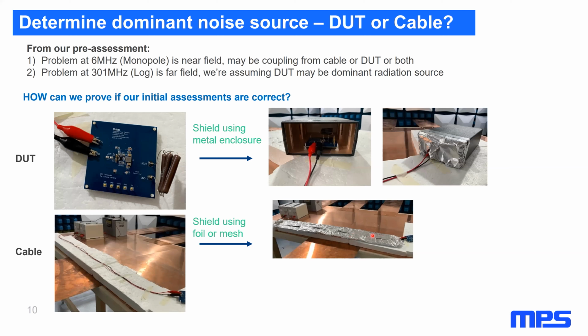I suggest that you insulate the cabling with either cardboard or wood on top and bottom before you wrap it. If you have a nick in the wire and you wrap it like this, you could short out your battery or cause your board to fail, and we definitely want to avoid these situations. So be careful, try to put some insulation around your wiring. Then you can wrap foil and tape it to the copper table so it has a very good ground connection.